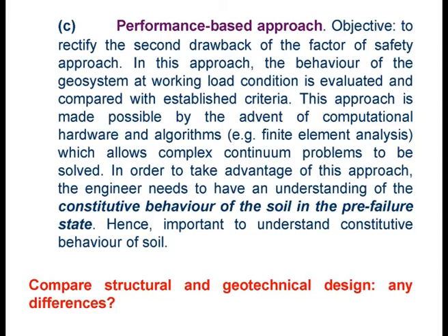Okay, but when you go into things like deep excavation, tunneling may not be so important, but deep excavation in a city area like the center of Mumbai, I think you probably will need a little bit of FEM to help you get some feel of the ground movement. That's the kind of thing. But of course, if you are doing classical foundation design, I think factor of safety is as good as anything.